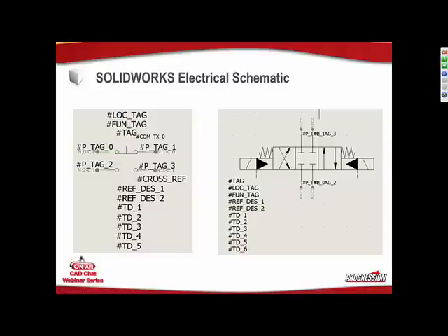If you're familiar with AutoCAD, it's just DWG blocks. So you have attributes in those. Attributes is pulling information from that SQL database to fill in the information about that particular symbol when you add it to a drawing. And again, it doesn't really matter whether it's electrical or hydraulic. A symbol is a symbol.